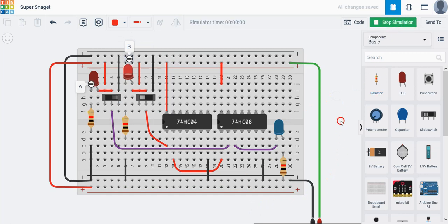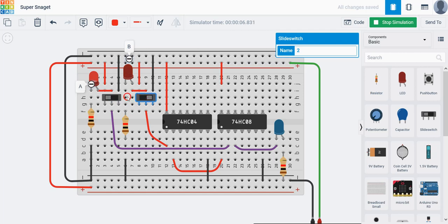So if I start the simulation again, you see that my chips, in fact, do not give me any trouble anymore. And this switch is on, so this LED is on. This switch is off, so this LED is off. If I toggle, then the LEDs show me what I'm providing as inputs. Now, this LED here doesn't seem to respond, and the reason it's not responding is because I connected it wrong. This one here is the anode, and it is the one that I need to power. This one here is the cathode for the LED, and that is the one I need to ground.